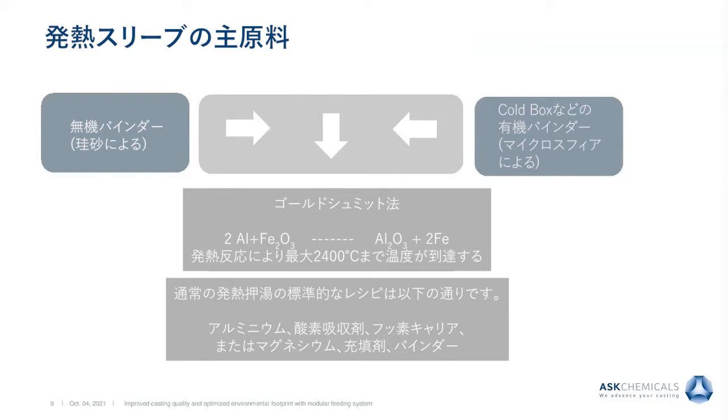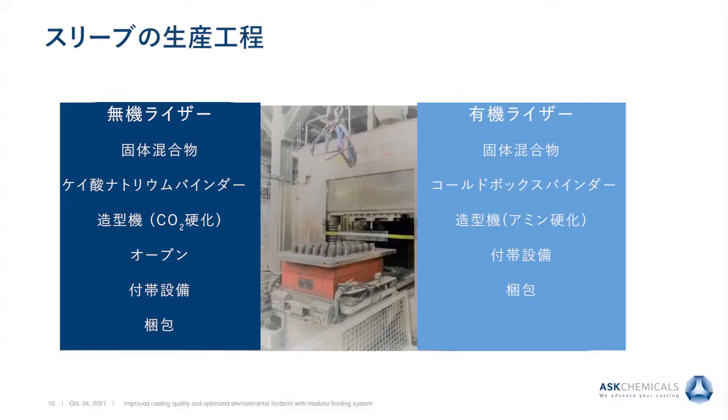So what is the difference in fabrication of risers with these different types? You have a solid mixture of the exothermic powder and the filling compounds. In both cases you have a binder: sodium silicate in the case of inorganic risers, and in our production of organic risers, polyurethane cold box binder.